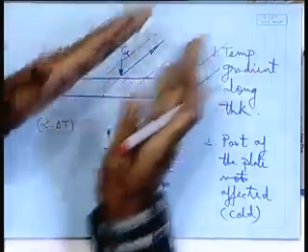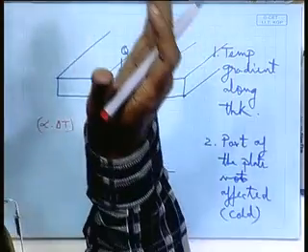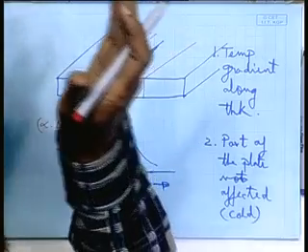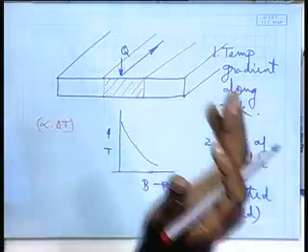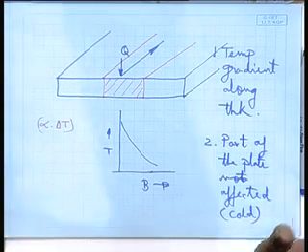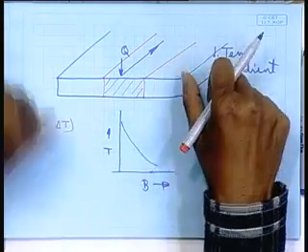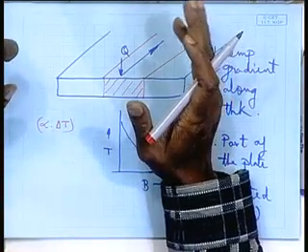So, we may conclude that a part of the plate along which the heating is being done, a neighboring part of the plate along with the heating zone, is subjected to some kind of thermal expansion, whereas the rest part is remaining cold, not expanding. So, what is it doing? The rest part of the plate is acting like a vice. That analogy is coming.